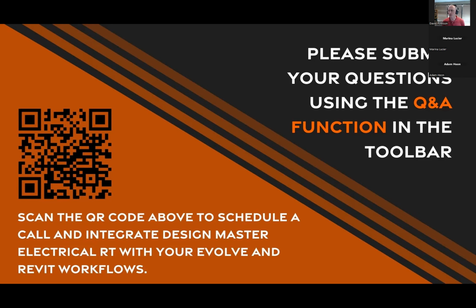Can Design Master Electrical export tables of breaker settings, like what would be needed for a power study report? We don't at this very moment. We are currently developing that so that we can actually export these. They're essentially going to be shared parameters that end up on the panels, and then you can schedule them in Revit. So right now, the only place we export the settings is here in these graphs, but we're going to export them as separate shared parameters so that you can then schedule them for things like power study reports and whatever other purpose you have for them.